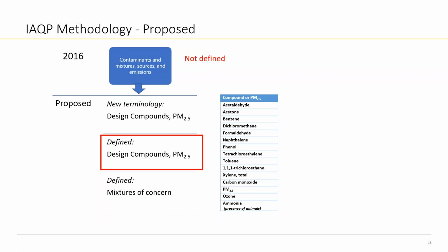There are four simple questions. First, is this compound expected to be found in the indoor air with a reasonable frequency at a concentration relevant to the design target? And by design target, I mean concentration limit. Number two, is there a design target that has been proposed by a cognizant authority? As you know, ASHRAE does not make up health limits or concentration limits. ASHRAE merely references other cognizant authorities. Number three, does it seem reasonable to expect we can find a product emission rate for the building or product specific? Number four, if you want to measure it, can you measure it? Is there a method for it?